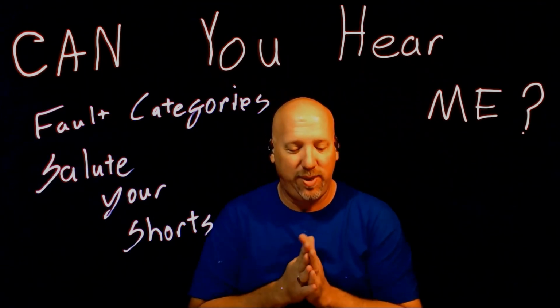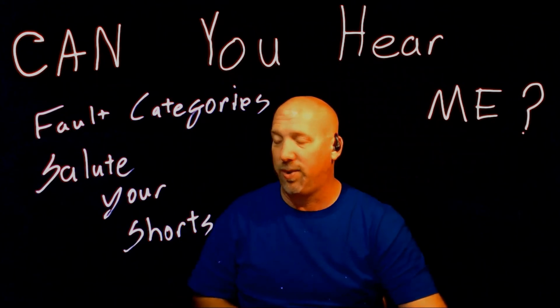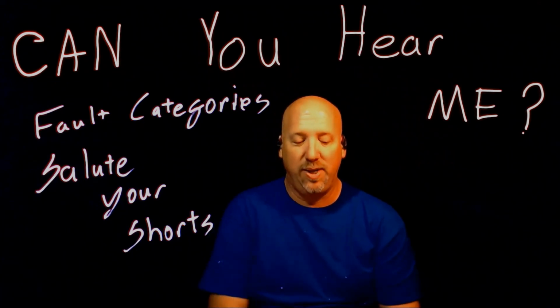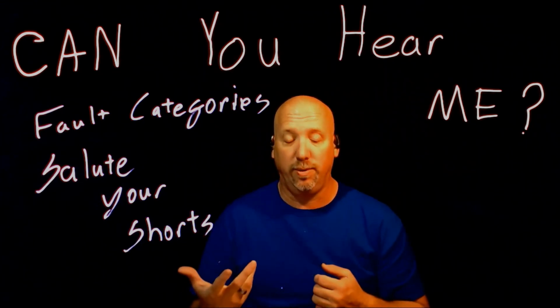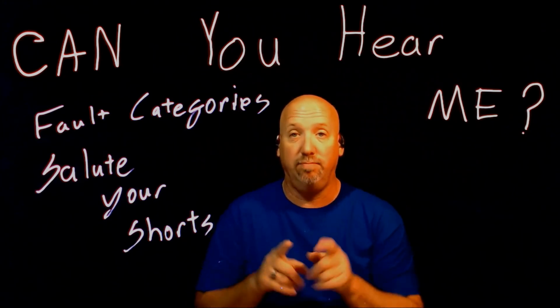Network shorts to power and ground are common, but it's a short to one of the physical network circuits or a short inside one of the network modules. So you have to think about where your shorts are located. You can disconnect and reconnect modules one at a time in a loop until communication is restored. The last module you disconnected had an integral short. If there's still no communication, then your network harness itself is shorted. So be aware of that.